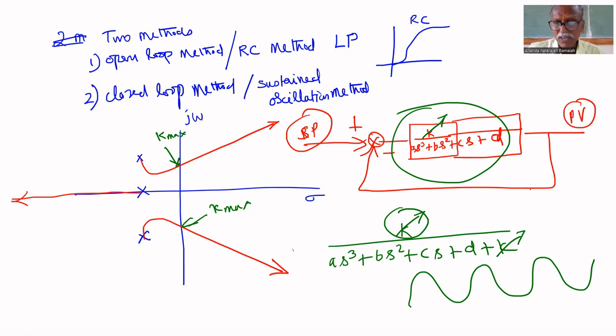Because you put 3 phase shifts here, 60, 60, 60. The components that you are using, how much tolerance do they have? 10% tolerance. You are getting 1 kilo ohm, which means it may be 900 ohm to 1100 ohm. It is not exact. Sometimes 5% tolerance means it varies from 950 to 1050. So it has tolerance. That's why even if you put the correct value, it is not correct, because it has some tolerance.